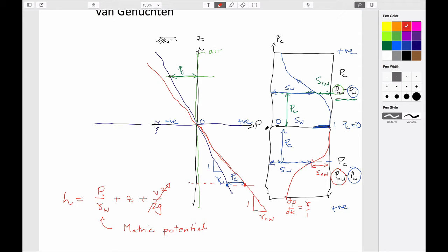Right? If we were to plot pressure here, instead of pressure, we were to plot hydraulic head. And we also plotted that with depth. And we took our datum as z equals 0 here. What would that curve look like for these pressure curves? Easiest to do if you're going down. If you start here, what's the hydraulic head here? Elevation is 0. What's the pressure here in gauge?